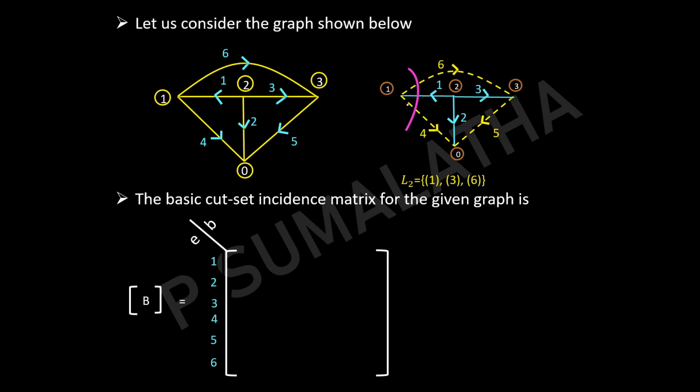So now what is the direction of this cut set? The direction of the cut set will be the same as the branch direction. Whichever branch you have cut, that branch direction will be given for this cut set. So this is the direction. Let us consider this is cut set B1. Let us mark the element values corresponding to this cut set B1, including element 1, element 4 and element 6. That means these lines will carry the value 1, remaining lines will carry zeros.